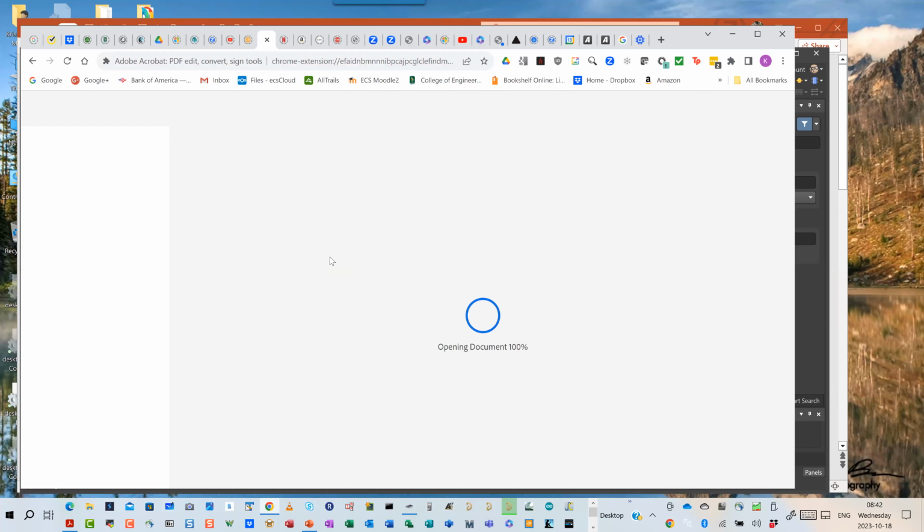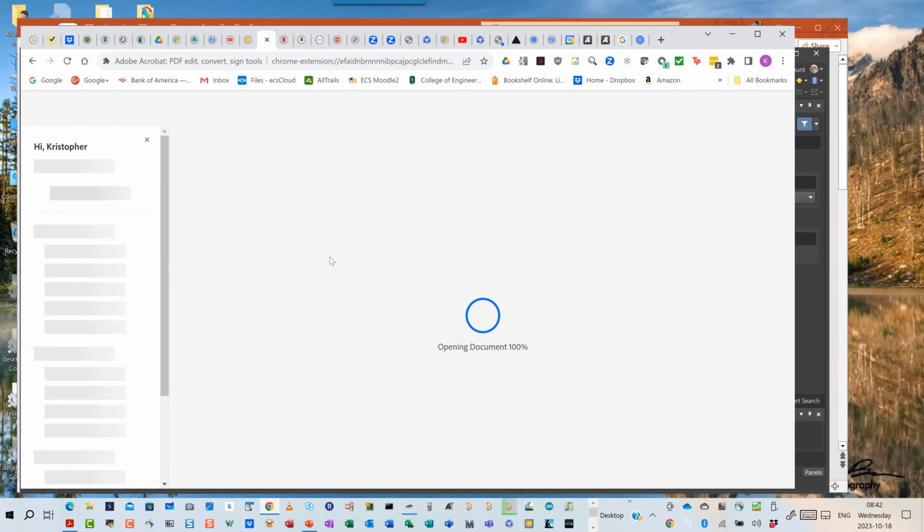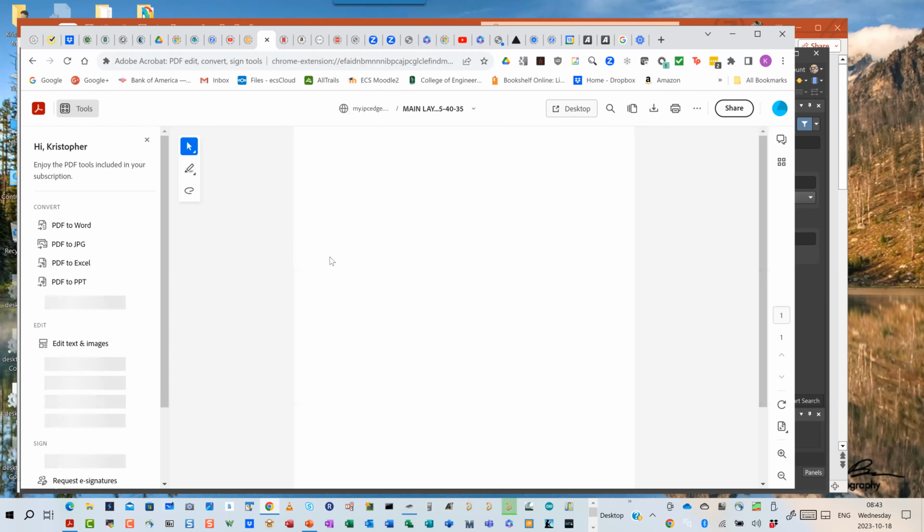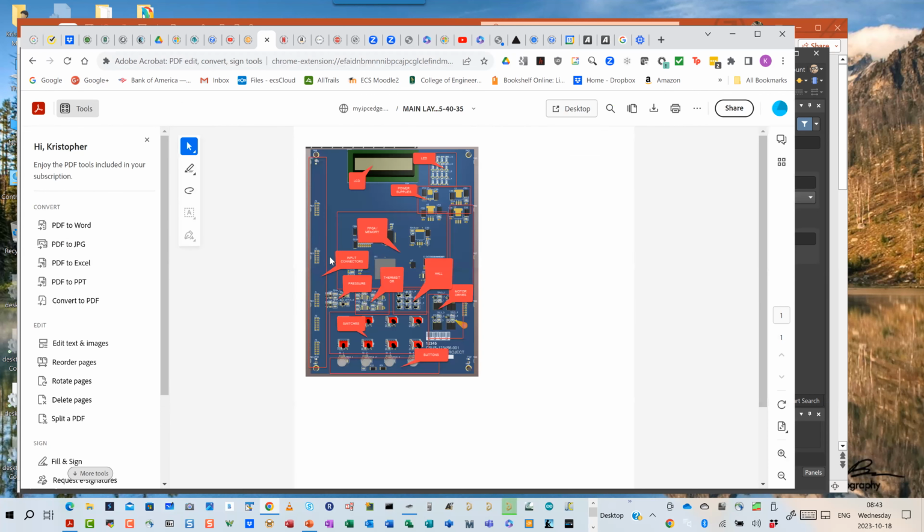Take this as a rough concept level of where things should be: LCD at the top center, LED displays in a 4x4 array, power supplies over here on the right, digital stuff with the FPGA and the memory somewhere top center, pressure transducers over here, thermistors here, Hall effects here, motor drivers here, switches roughly here, buttons roughly here.